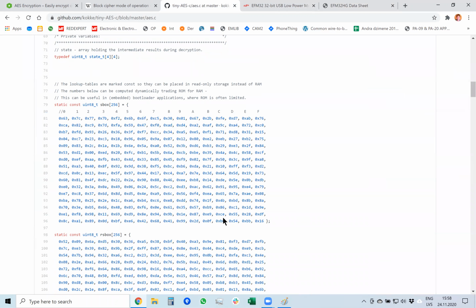If you want to take the cheapest microcontroller that you can find, it will not have AES hardware acceleration built in, but you can use code. But if you want your chip to be more power efficient and calculate AES encryption faster, you would buy a chip with AES built in.